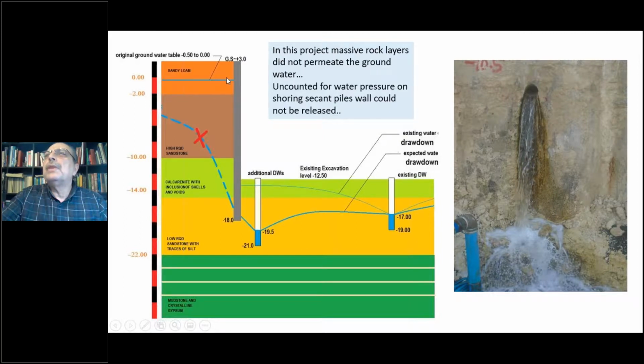With the ultra deflection that I had at the top near the first row of anchors, I understood immediately that the water pressure is working and it is not, as designed, getting lowered by the dewatering system. So we opened holes in the shoring wall to decrease the pore water pressure. And with these holes, the deflections stopped immediately and even went back.